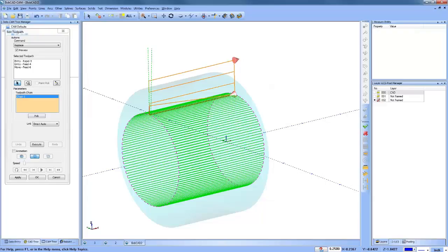So basically you can draw anything and make it your toolpath, either center line or profile offset. Yes, Jerry, you can draw anything and make it your toolpath. It's going to be center line because all you're doing is taking the wireframe geometry that you have and replacing it. So any compensation or anything like that, collision checking, all of that is going to be up to you. Okay? All right. So hopefully that answers your question.